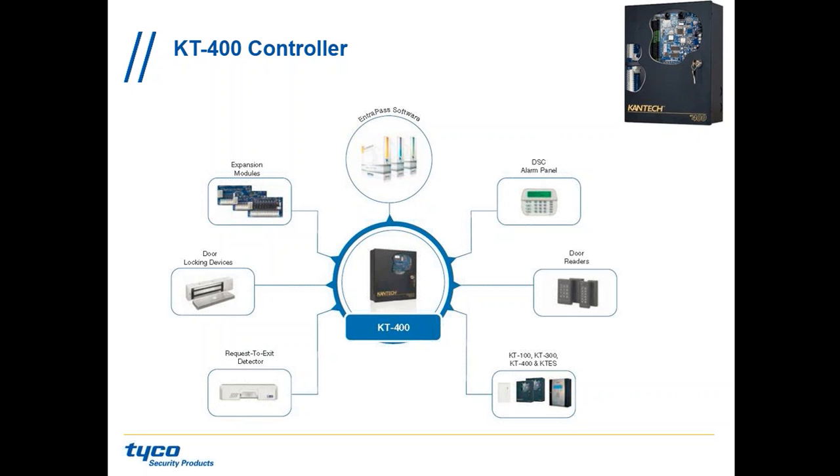And we said, my friend, this can be done easily with one KT400 that can manage 4 doors, so more than they need. They needed 3 doors. And we can use input board, and each input board in the KT400 manages 16 input, and they have enough. So one controller, and about, if I recall perfectly, it was 13 input board to have the quantity they needed. And so the KT400, it's a 4-door controller